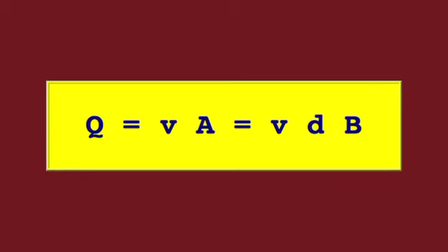In practice, a hydraulically wide channel can be approximated as a rectangular channel of depth D and width B. A unit width analysis is applicable in hydraulically wide channels. The discharge per unit of channel width, q, is